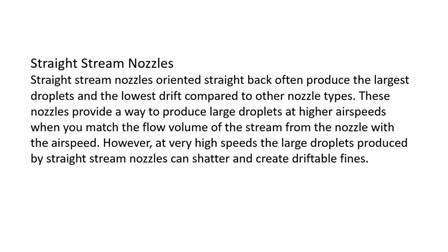These nozzles provide a way to produce large droplets at higher air speeds when you match the flow volume of the stream from the nozzle with the airspeed. However, at very high speeds, the large droplets produced by straight stream nozzles can shatter and create driftable fines.